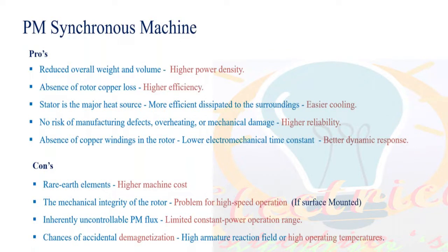And one more thing is, compared to the induction motor and other counterparts, it is quite easier to cool. But still, temperature issues are there in the PMSM motor because of the permanent magnet. And high reliability. Manufacturing wise, yes, it is better compared to technologies like synchronous reluctance motor and switched reluctance motor. Manufacturing wise it is actually good, especially compared to synchronous reluctance motor. And moreover, a very important thing is dynamic response. The motor should be able to respond immediately when the driver presses the accelerator.